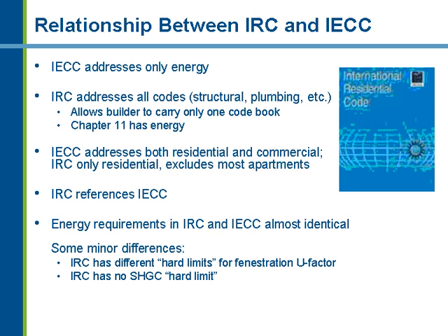The IECC, as its name suggests, addresses only energy, whereas the IRC is a consolidation of all the codes, structural, plumbing, etc. The intent of the IRC is to give builders a single book to carry around, and there's one chapter in there that deals with energy, Chapter 11. While the IECC addresses both residential and commercial, the IRC, of course, as its name implies, is only residential, and in fact it excludes most apartments.